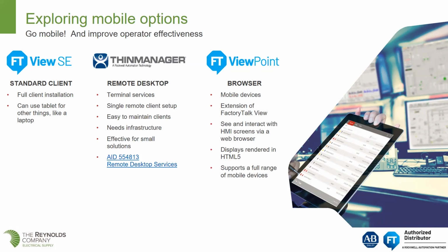We could also use FactoryTalk Viewpoint. FactoryTalk Viewpoint is an HTML5 web server that is provided with FactoryTalk View SE. With HTML5, the same displays are rendered on your phone as they are on the operator screen, and that's another option, to use a web server. Typically, the web server would be deployed for view-only screens, but it is possible to get some control out of the web browser.